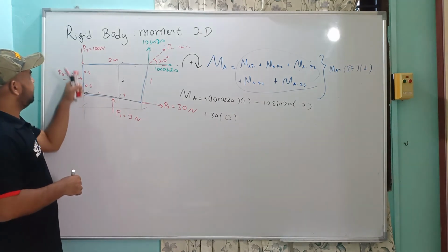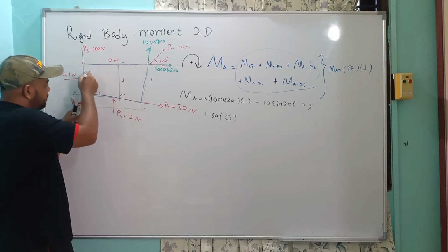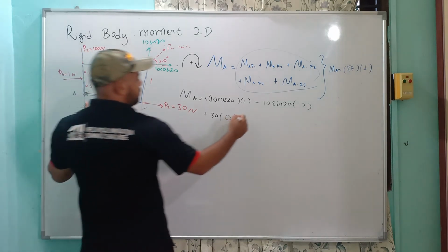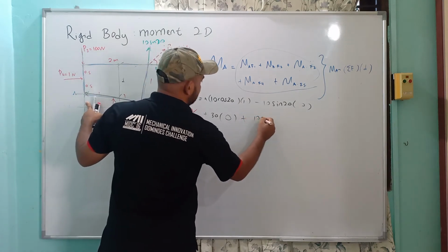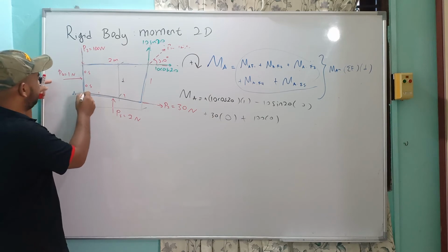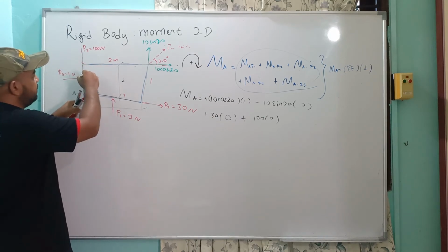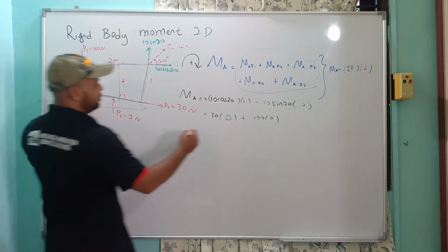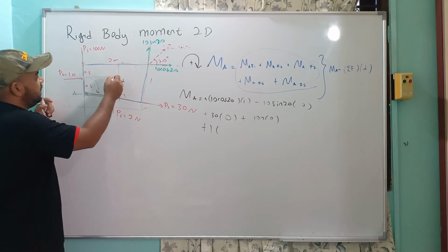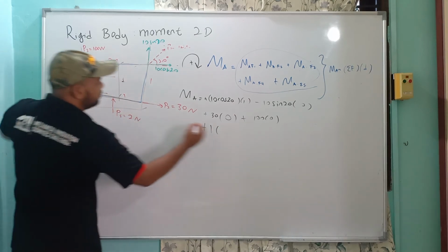P3, same. This is the force. Make a line of action of the force, you see that it goes through the point. This one also will be 0. So plus 100, 0. Okay, and then now P4, you make a pin here, push this direction, so we will turn clockwise. So plus 1, the distance is, first line, second line here, and then this is the distance 0.5.